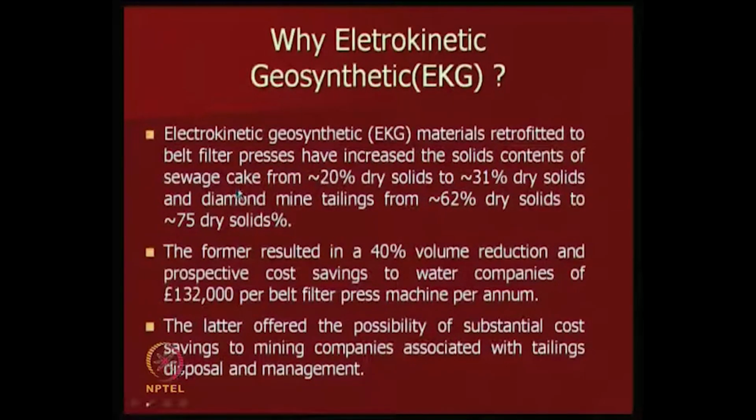For example, if you are trying to handle sewage, the water content is going to be very high. So what we do is try to increase the solids content there. There are different techniques called centrifuges and belt filter methods, where we make some arrangements to remove the water.